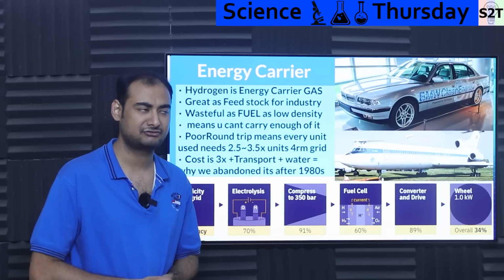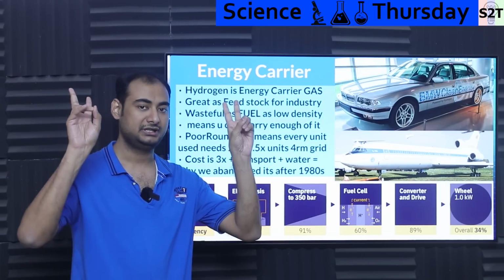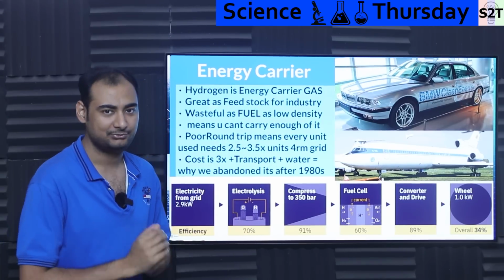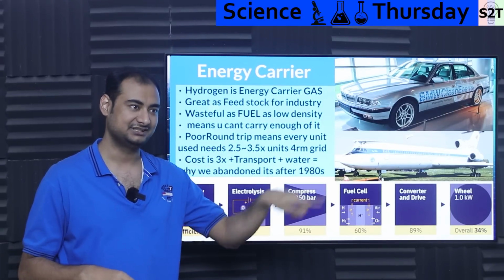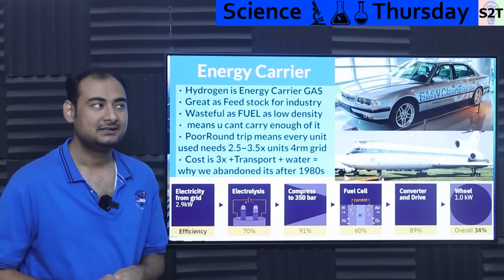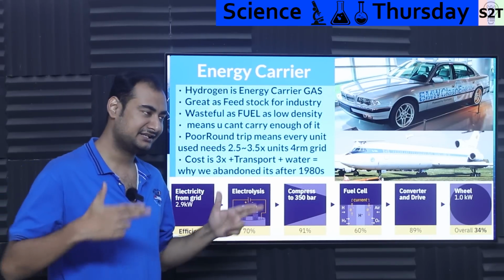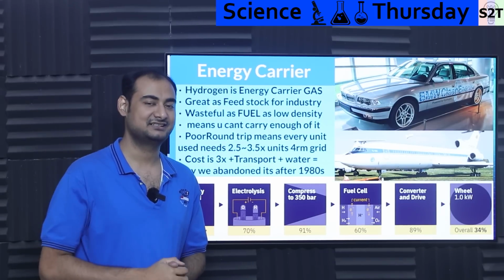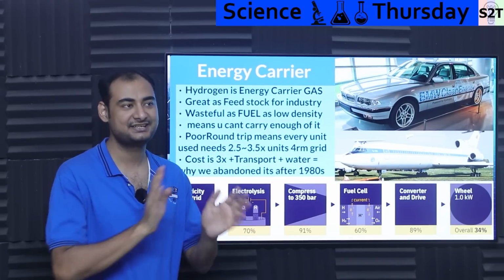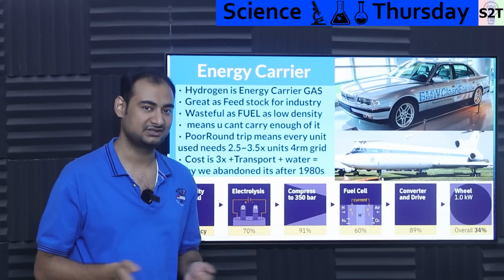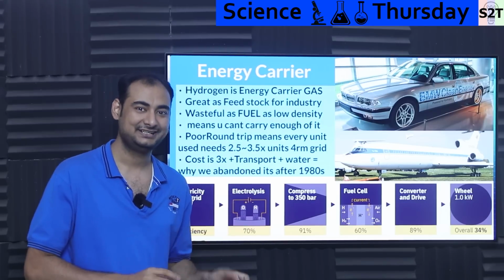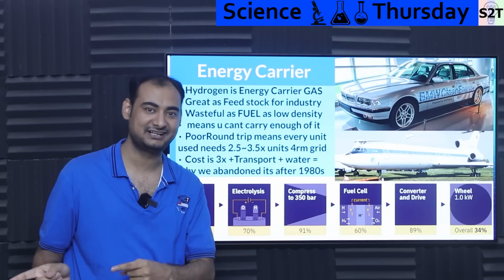So okay, where are we getting that hydrogen from? We are doing steam reforming of methane, CH4. Basically, we are cooking that puppy, breaking it up into carbon dioxide and hydrogen, and that hydrogen we are utilizing. So if people are thinking that, hey, we are running a hydrogen car, it is so efficient and all that, no, the carbon dioxide is coming at that steam reforming plant, not at your car. It's just out of sight, out of mind. You're still producing a bonkers large amount of carbon dioxide. It would actually be more efficient in terms of CO2 production to just use the methane directly.